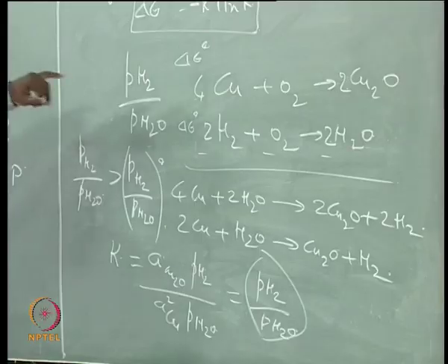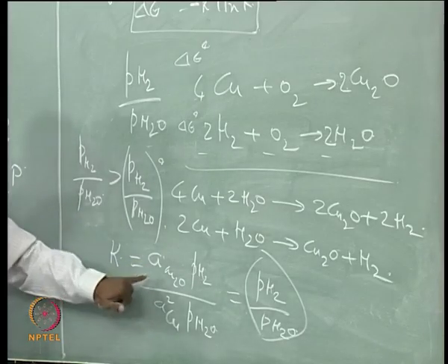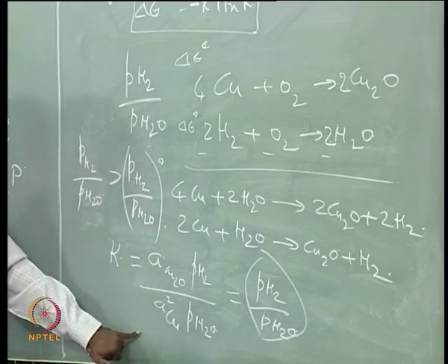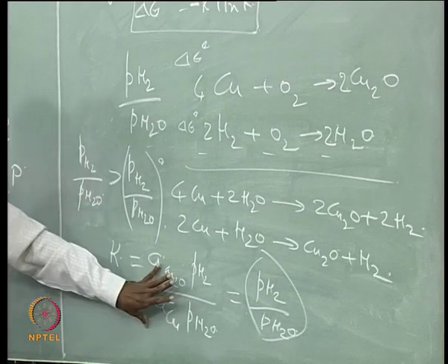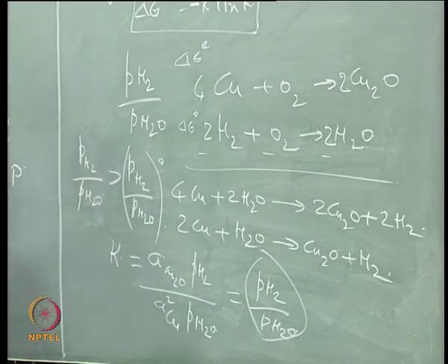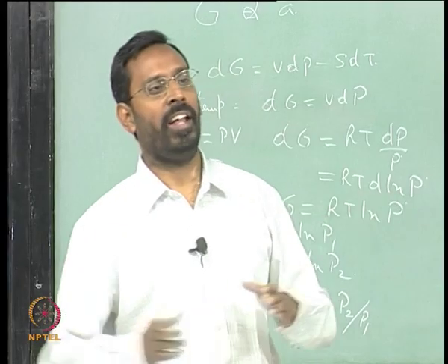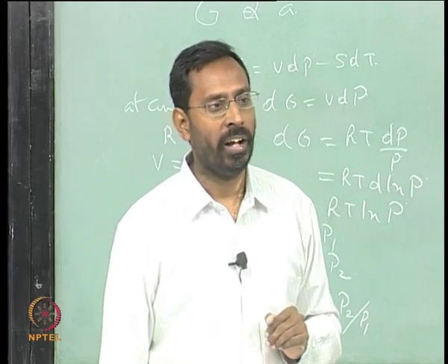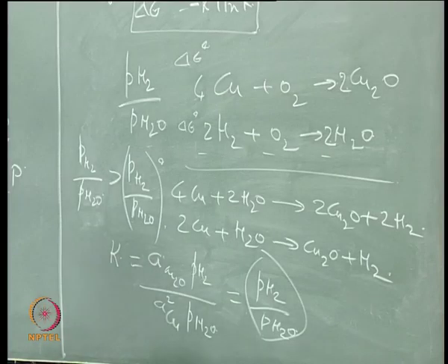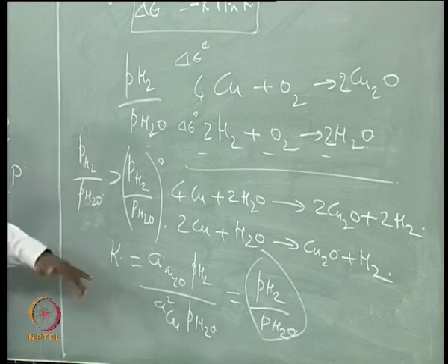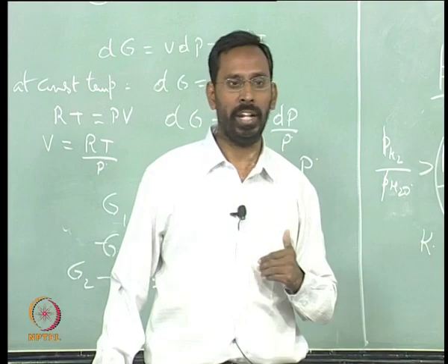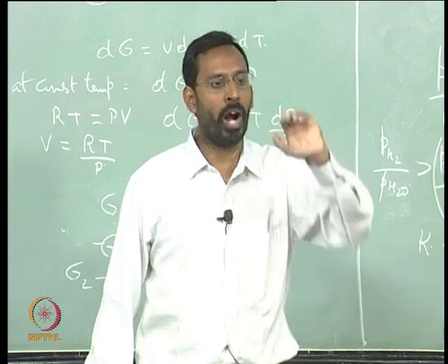So, the actual activities that we are talking here, which we are equating to 1, this would not be true if I am considering alloys. If I am talking of, let us say, a superalloy where there are various elements present, and I need to look at oxidation of each of the alloying elements, for example, in a superalloy, again I am heat treating at certain temperature to do hot rolling of superalloy.